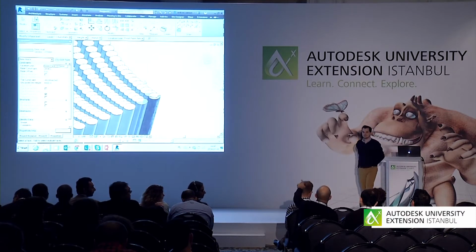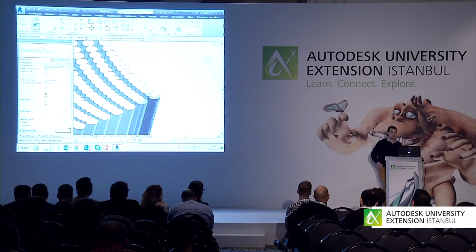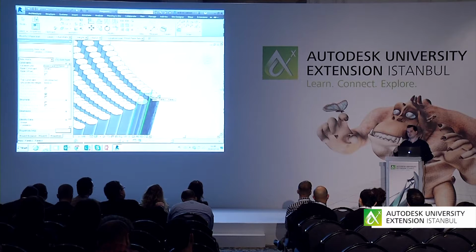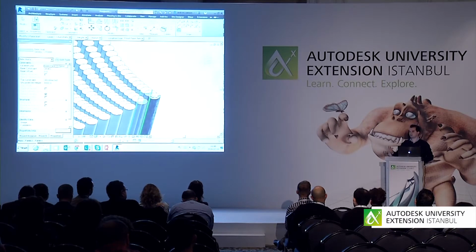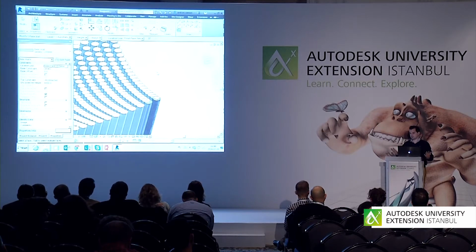What if you update the Dynamo file, but you won't update this one? So, if I open Dynamo and run it again, it will create the SAT file again in that place. So the procedure would be I recreate the SAT geometry, I delete my mass, I reload it into the project, and then I have to place the walls again. So far it's not possible otherwise. You have to explode it, unfortunately.